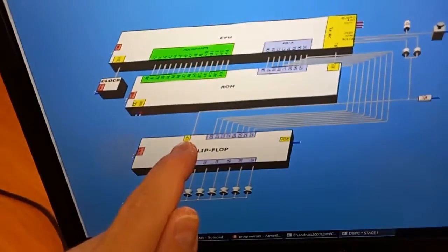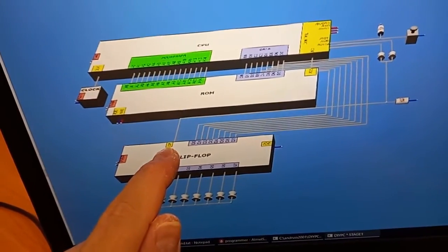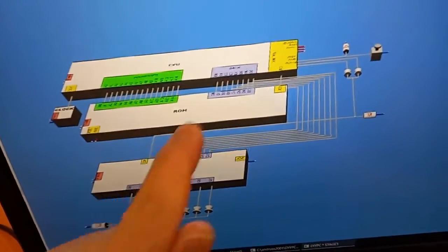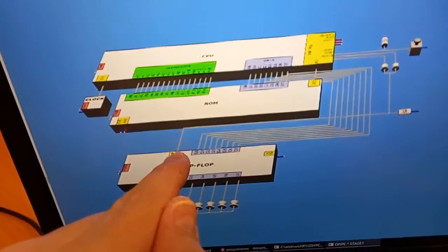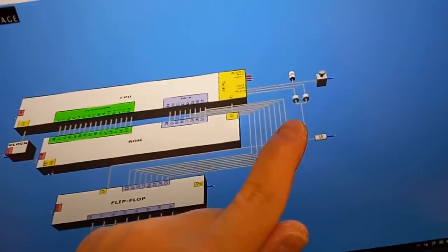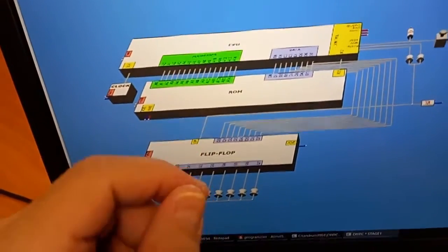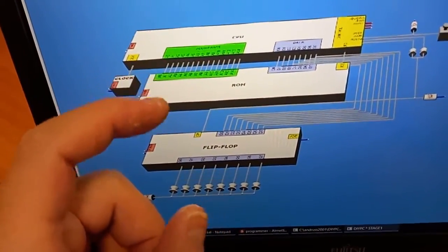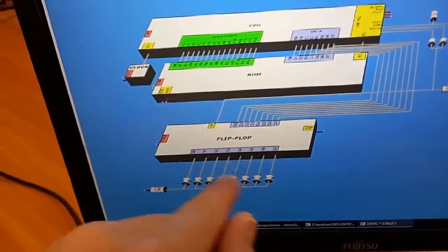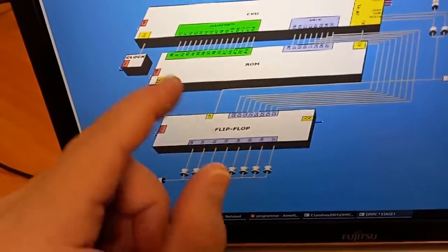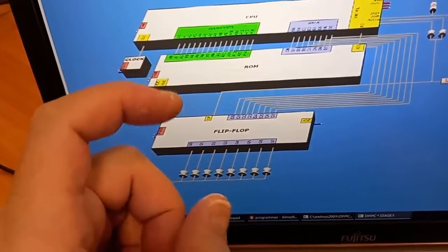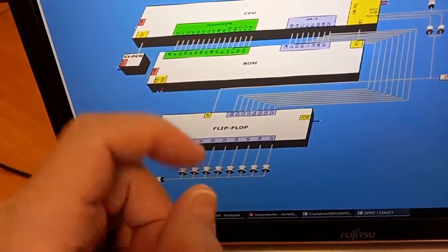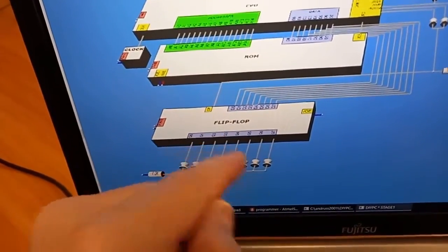When the CPU has finished outputting, it pulls this pin back high, and when it gets high, it's like releasing the capture button of the photo camera, and the picture stays here. The picture that the flip-flop took when this pin was zeroed.